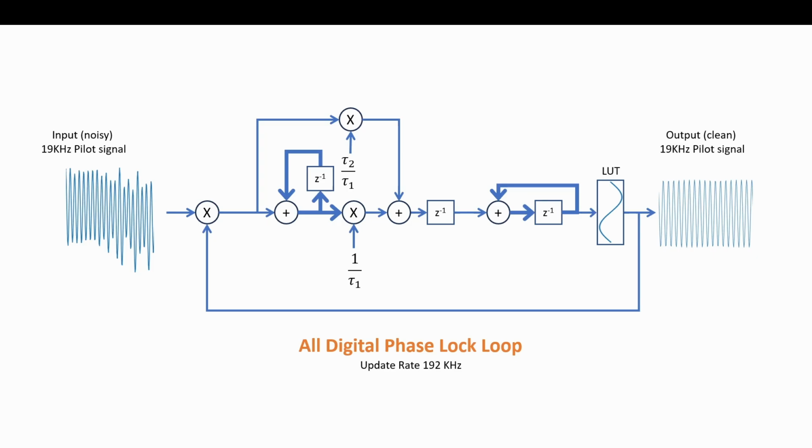And this block diagram is the implementation. So we have the loop filter, and do you recognize there's the accumulator. The z to the minus 1 is a unit delay, and our output is going to be the next input with the previous output. It's just going to grow. It's an accumulator. And then we see the proportional path coming around, and we have a gain constant tau 2 over tau 1. We have a gain constant here, 1 over tau 1. We're seeing P and I.